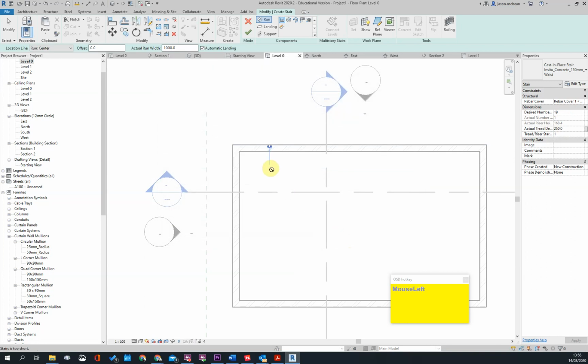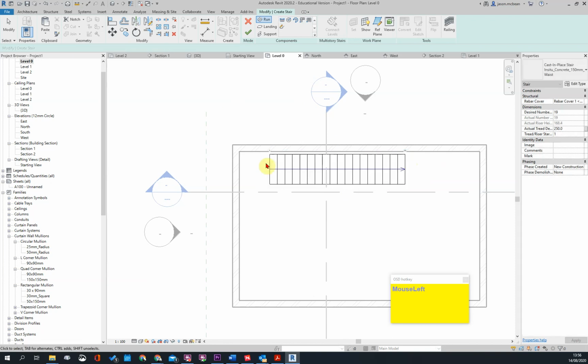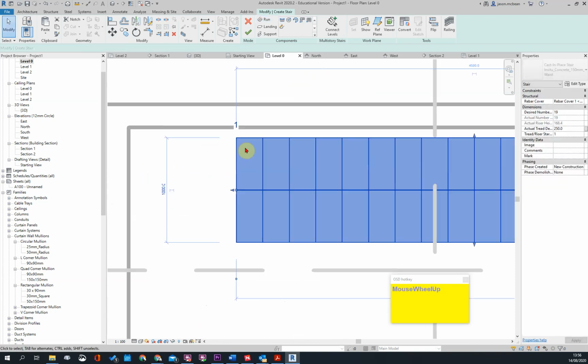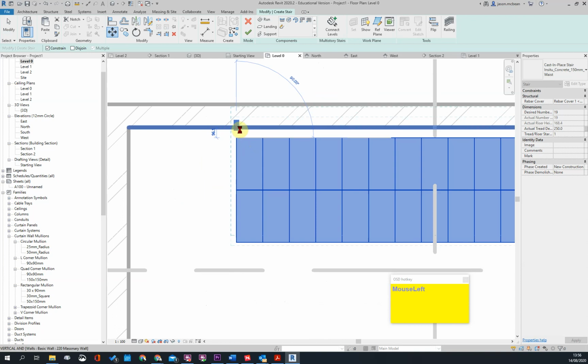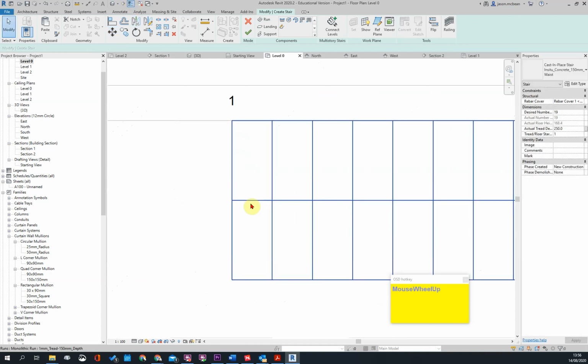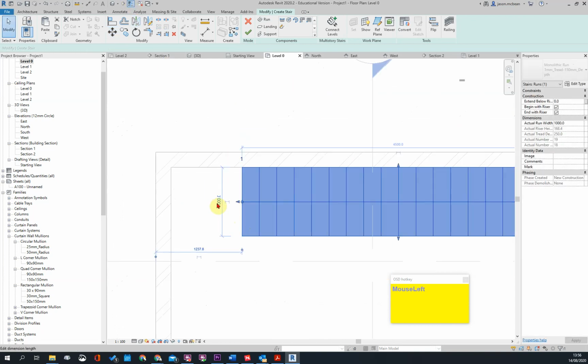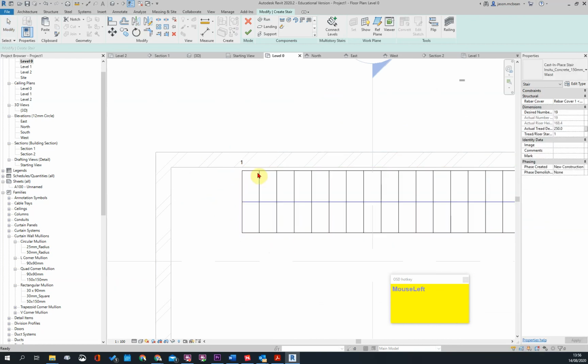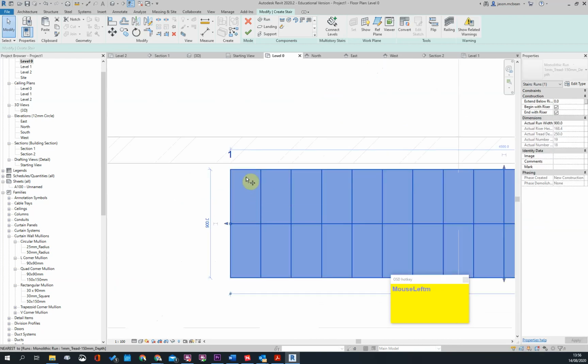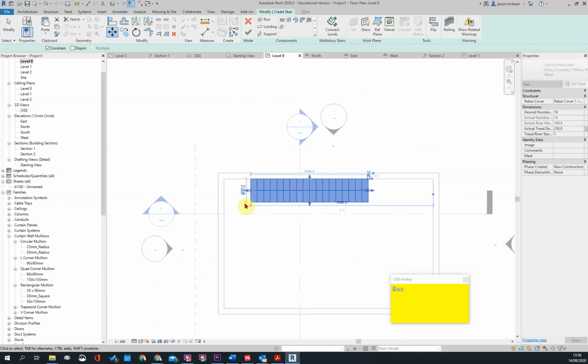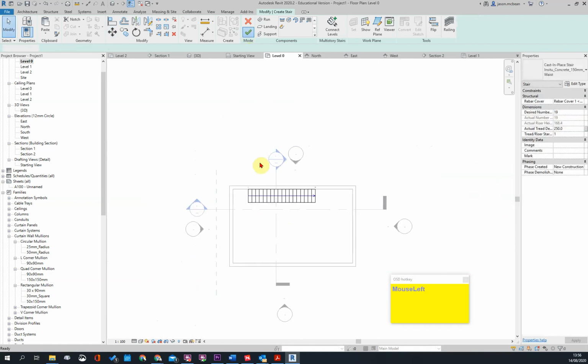So here I'm going to go from ground, and you can see when I'm drawing it tells you how many I've got left. So I'm going to say from there to there, that's how far I want to go. Okay, and then I'm going to move the staircase against the wall, switch off my line so I know exactly, and I'm going to change my width of the stair to 900 maybe. That's fine. Move this from there to there. Okay, finish my stair.